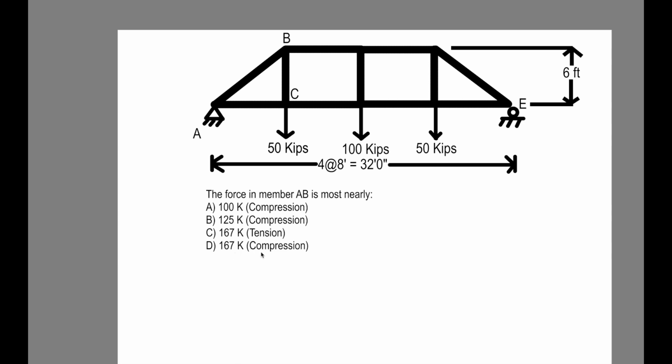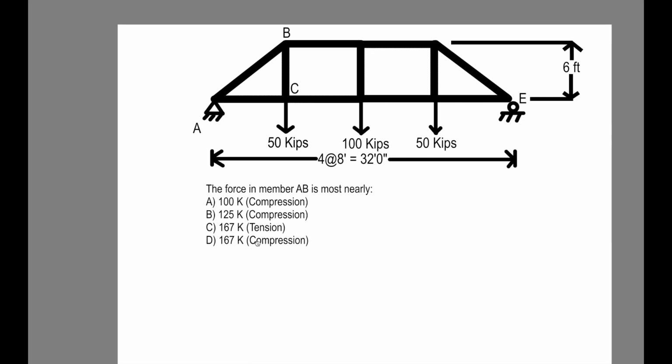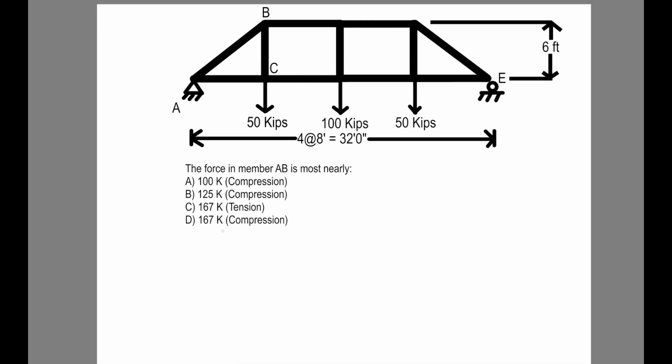Okay, so the first step with any truss problem is to solve for the reaction forces, right? And we want to think about this strategically, because we don't have a lot of time on the exam, so we need to use our time as efficiently as possible. If the question is asking us for the force in member AB, we want to focus on finding the unknown reaction force AY, because EY, this roller, is not going to help us solve for the force in AB.